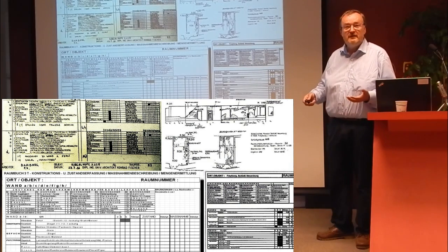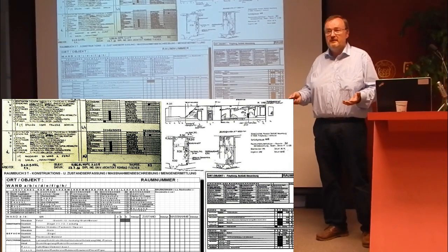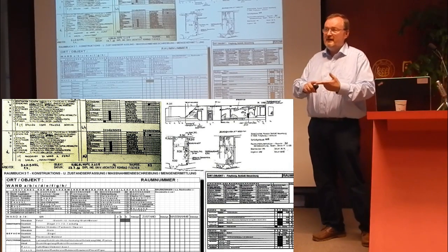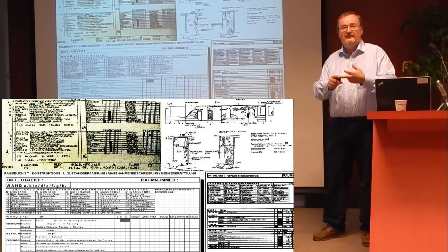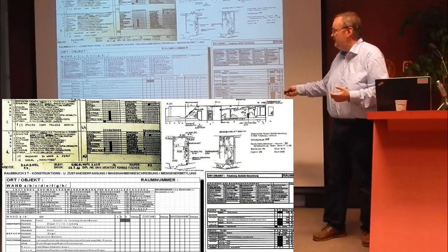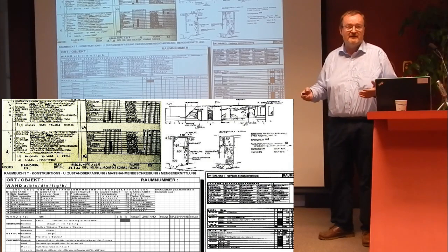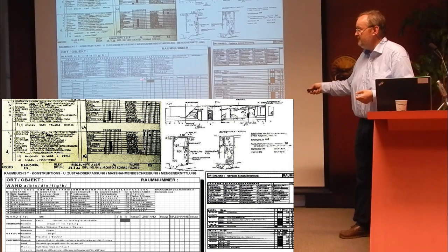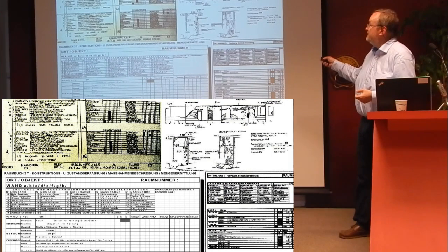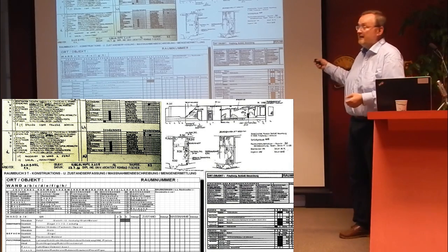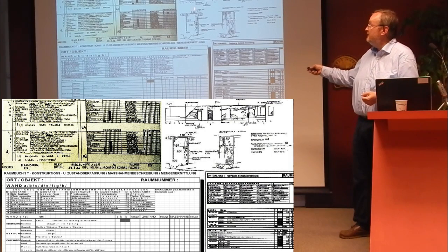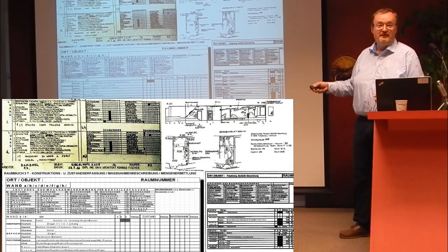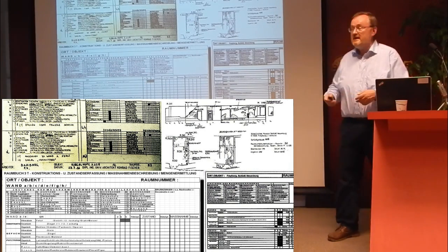And then I found out there is very few work to do. Perhaps it can stay because it's not a problem, or you will have a little correction in it, or you will have to renew the surface. So we have about 29 different things you can do at a damaged construction. So again, some numbers from the catalog given in here, and then in the second level you have a graphic documentation, the walls A, B, C, D, E, F, G, and the floor and the ceiling. And you will portray the damage.